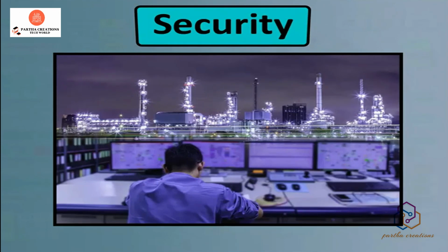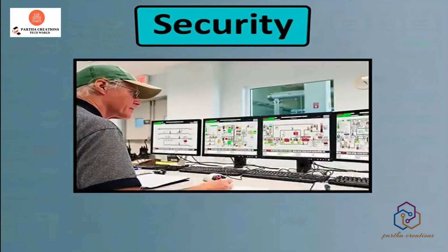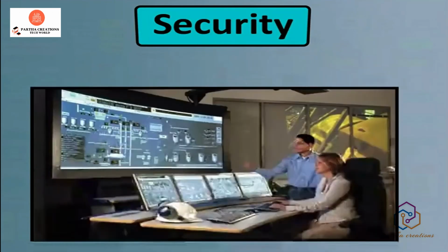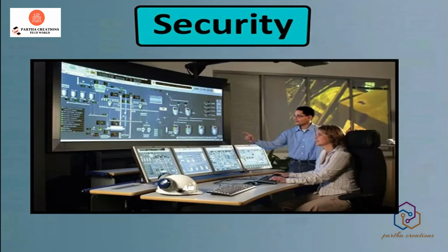For a window that is just to be monitored, where I only have to supervise, supervising authority would be given only to the supervisor. But whenever we want to do operations and there are options for control, not everyone can operate it. Only authorized individuals like the SCADA engineers can operate it. So to prevent everyone from accessing everything, we provide and enable security.